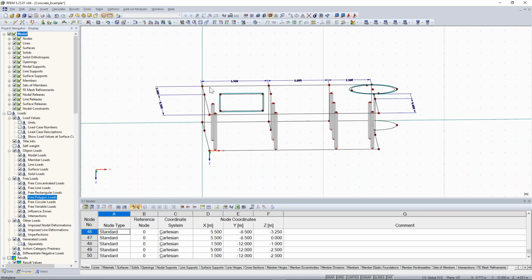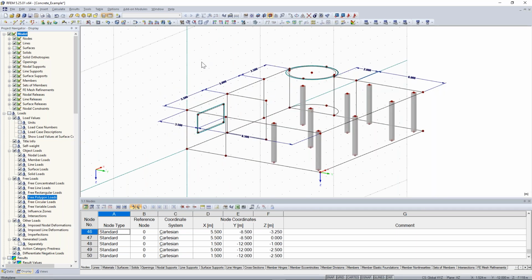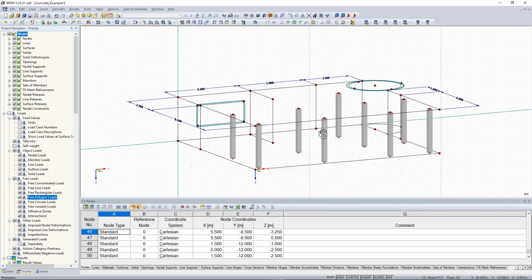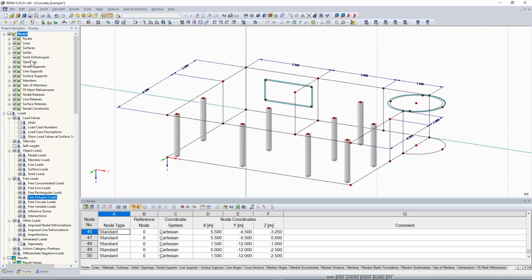And also maybe another tip: when you don't want to snap any grid points here, just deactivate Snap to grid, and then you can only snap these points or nodes of the structure. And this will make the workflow more fluent. This is also a very nice tip and hint. So you see, you will learn a lot of things here.